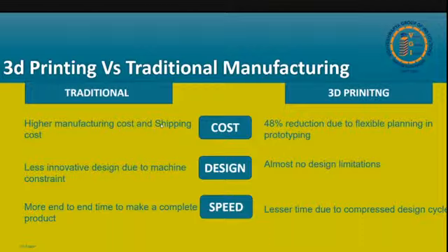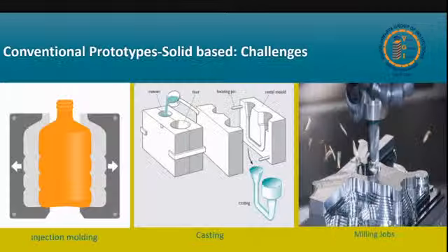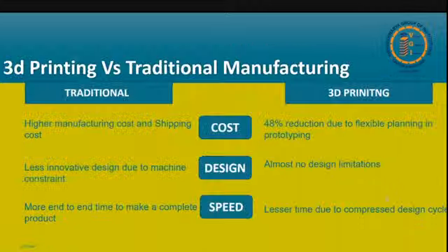in your hand. So nothing can be as fast as that, because with the other processes, you cannot go for the formative process. You cannot make a design today and go to the mold. Manufacturing a mold takes weeks, and the same goes with casting. You can do it fast in the subtractive mode, but these machines are very heavy and very costly, and you can spend a lot of money on that as compared to the 3D printer, where the part will not cost you as much, and it will be very fast.